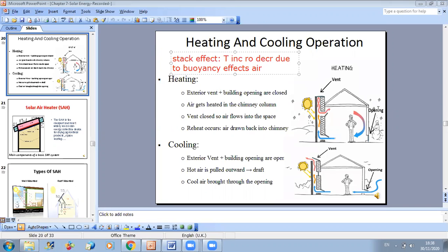But in the second case, it's like you're opening a window. Yes, but you don't necessarily need to have wind. This is what I mean. Even if you don't have wind and you have an opening here, air can circulate inside the space. If you have wind, your efficiency will increase a lot, because you will combine the pressure drop effect with the stack effect. And then the question before with Bernoulli: we put V1 equals V2, that's why we cancel them?